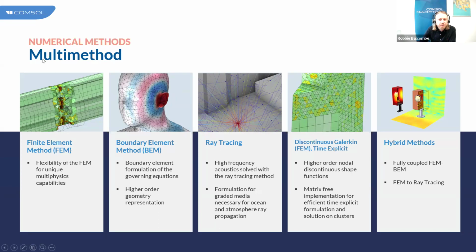So on the left-hand side, we have the finite element method and we have the boundary element method. So these numerical methods are based on us tessellating our geometry with a mesh and computing the solution to our acoustic problem on the nodes within our mesh. The nodal points will be distributed at the element vertices and also midway along element edges, depending on the type of element that we're using. But the key thing here is that we are using this mesh that we apply and tessellate the geometry with.